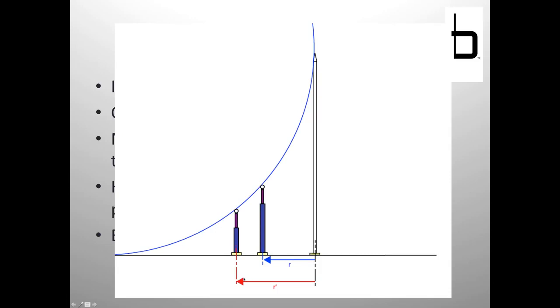Yeah. It's kind of the brim of the witch's hat. There you go. That's exactly right. So we're getting closer to the brim, away from the center. Right. So if our equipment is shorter, we'll have more radius of protection, meaning we can put our equipment further away. So this is something that we can calculate, right?